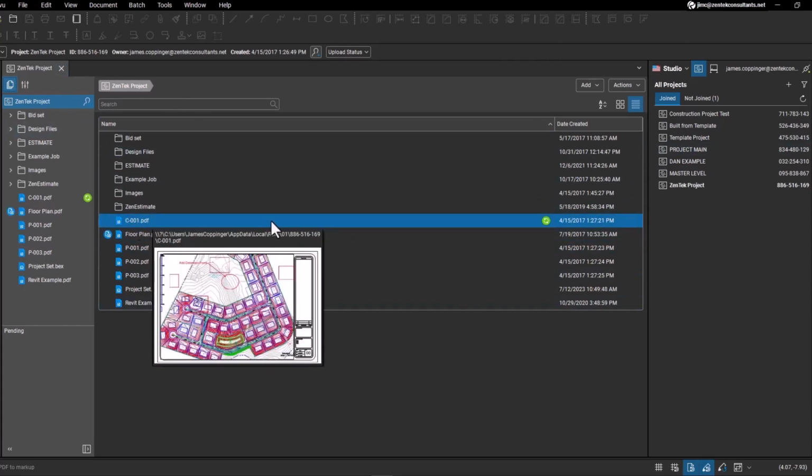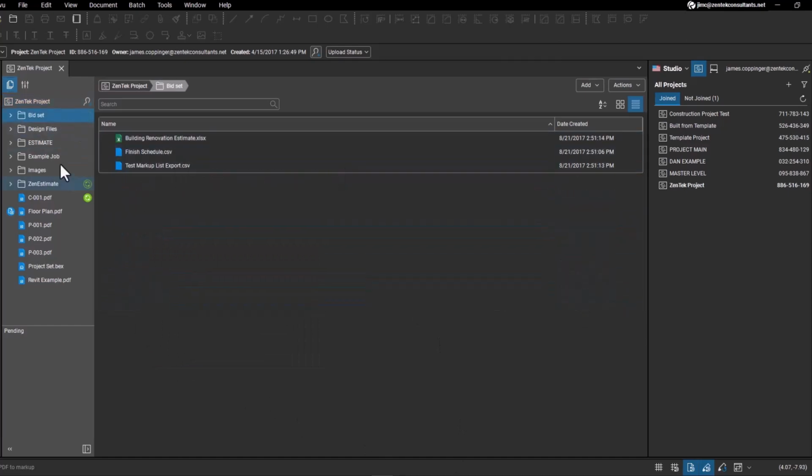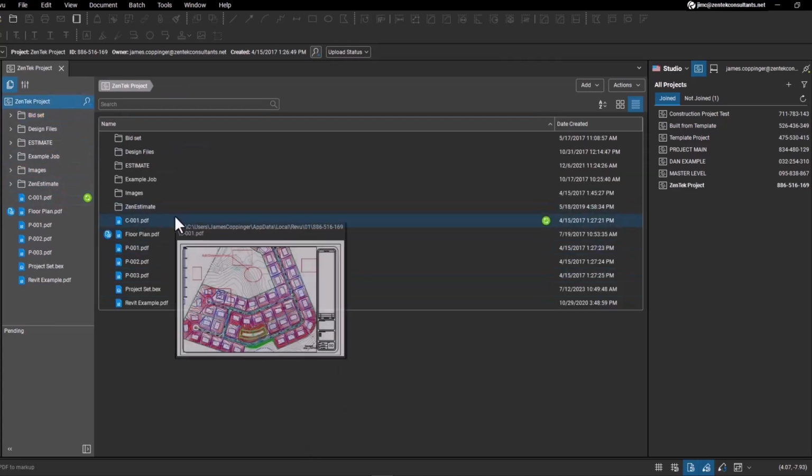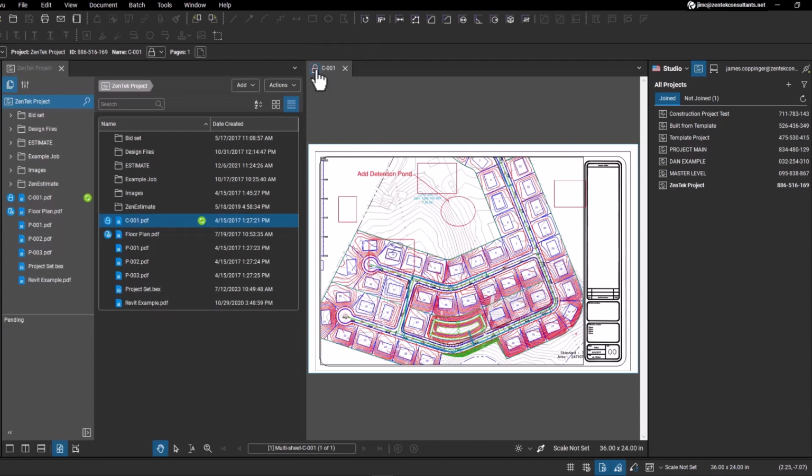in Bluebeam, you see that right away when it opens up, there's a little lock icon on it up here. It's in read-only mode. Everybody is restricted right now to just looking at the file. Can't edit it, can't actually make changes. So much so that Bluebeam will actually lock out its own tools when you're in that read-only mode. You can't even use basic markup features here. It wants you to be consistent with that checkout process.